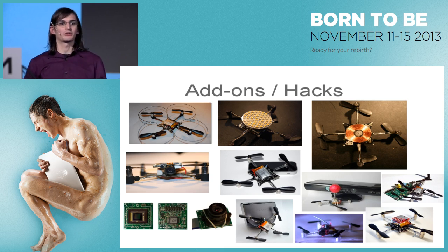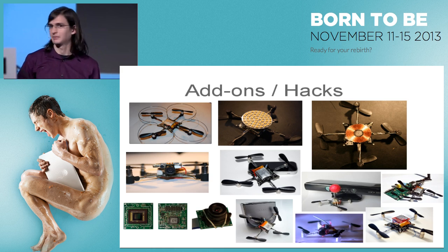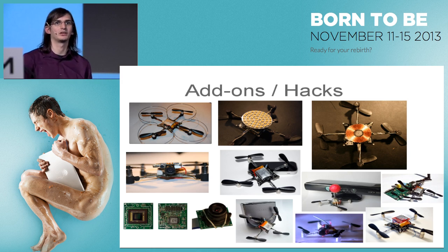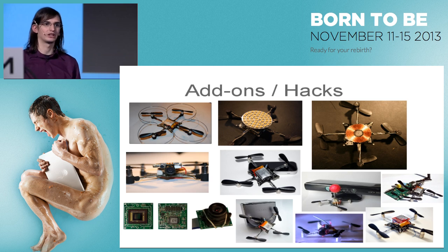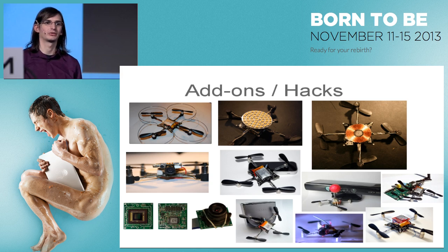I already talked about the Raspberry Pi, so we can control Crazyflie from any embedded system. We also hosted a master thesis, which is a master project. The goal was to do a digital FPV that would send images back through our radio, which is very hard because our radio is not very high bandwidth. We have 400 kilobits per second of usable bandwidth. So they did their own PCB with the camera and everything. It was a bit on the heavy side, and as I said, the bandwidth was not enough for enough frames per second. But it was a nice try.